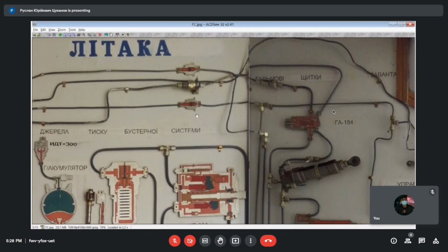The tail part of the fuselage is detached, so as to remove the engine, install a new one, and next attach it back. So in this cross-section, hydraulic lines should be quickly detached without leakages, and next quickly attached, also without mechanical impurities and air locks inside. So with self-locking valves, devices which provide quick disconnection and quick reconnection.